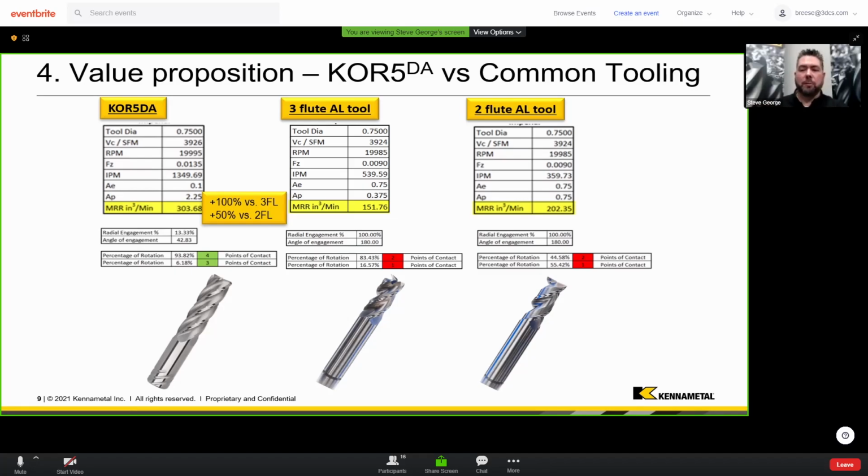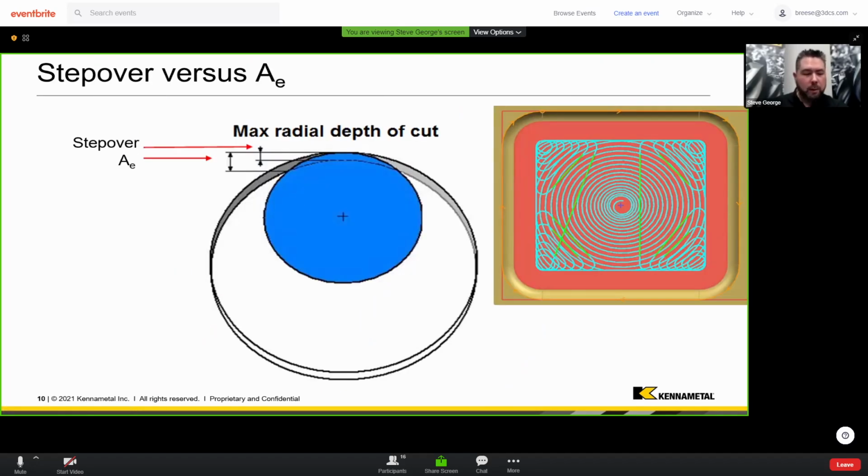Usually I can take a smaller machine, a smaller spindle connection, and get more out of it with a dynamic cut. One thing to keep in mind is if you get into something like aluminum with extremely high cutting speeds, RPM available, you might be looking at a very, very fast table travel. And that's then something to keep in mind.